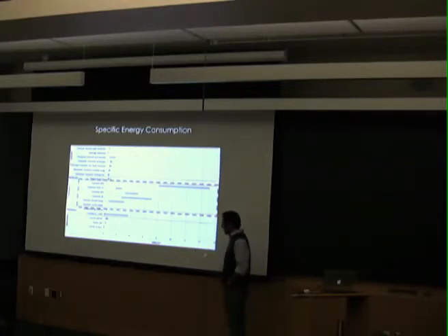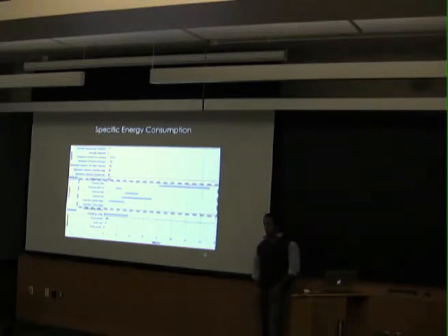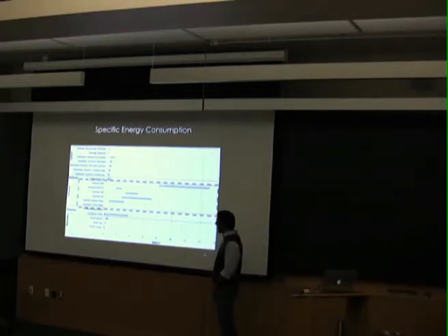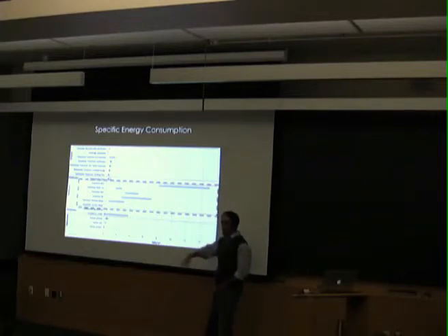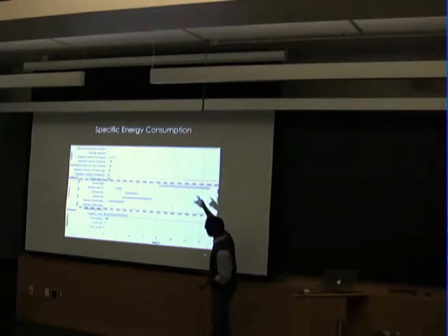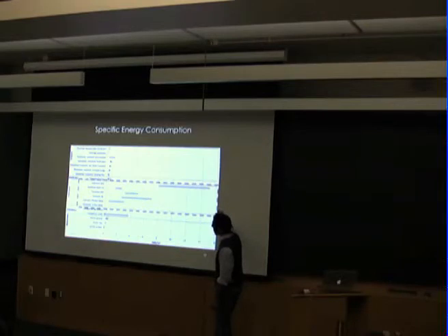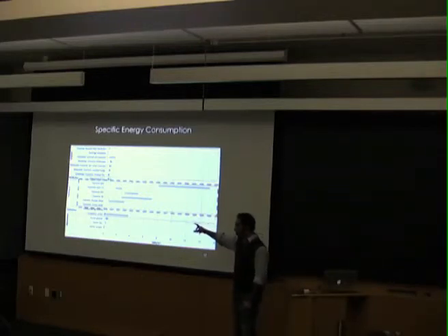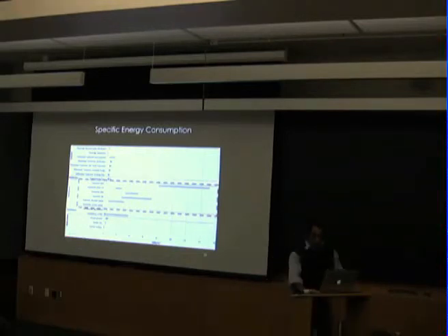This chart shows electricity consumption, so where the treatment process used fossil fuel, they converted that number into the electricity equivalent in kilowatt hours. At the bottom is abstraction, which means getting the water out of the ground or from a reservoir. And at the top is disposal, which means treatment or discharge of various types. Many of the treatment processes in the center are the desalination processes, which tend to have very variable ranges, but also on average much higher energy consumption per cubic meter of water.